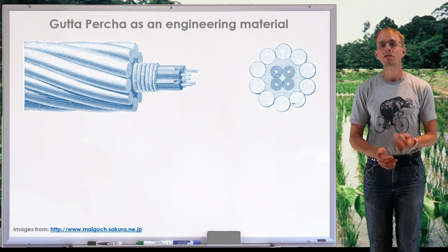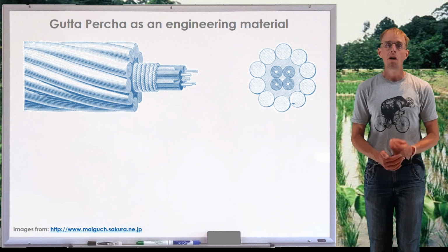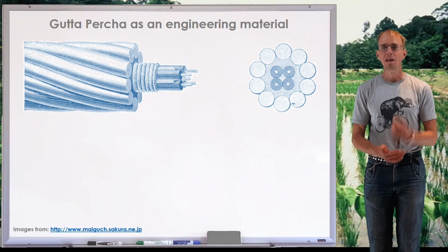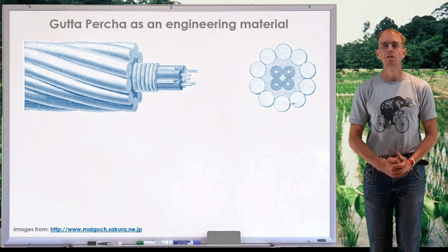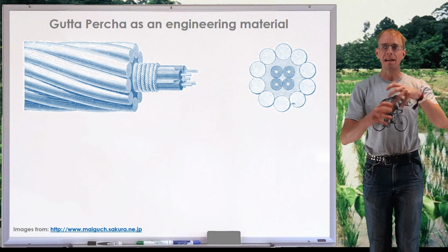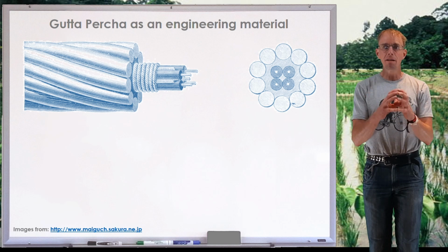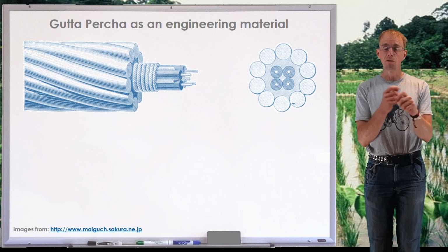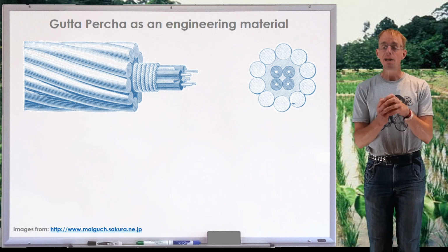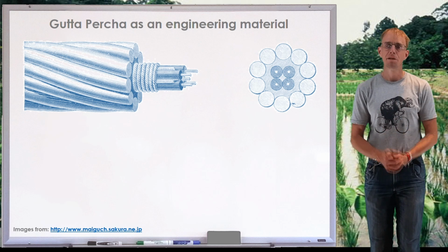So the first transoceanic telegraph cables, telegraph being the forerunner to telephone, were constructed using gutta-percha as the insulator between the electrical conductors. And so the diagram I've put there on the board is of a cable-based outer, much as you'd get a sort of a structural cable. In the middle of that cable-based outer, you've filled it with gutta-percha. And then you've got your individual conducting strands, of which there are 4 in this particular picture, each of which are cables covered in insulator, the insulator being gutta-percha.